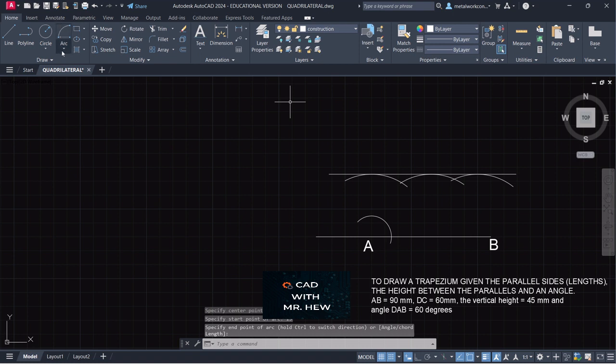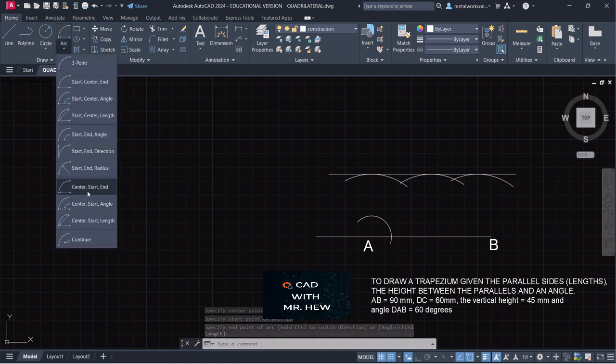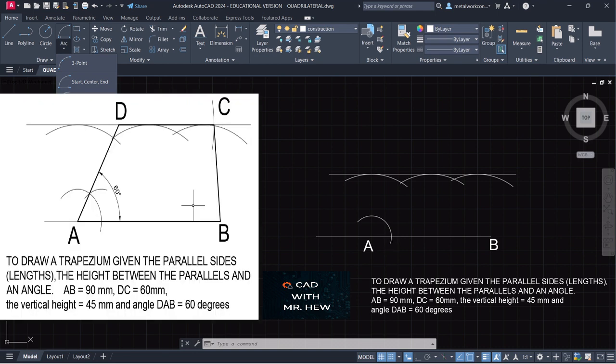What we're gonna do, we're gonna draw another arc with the radius equal to 15 from the intersection where the arc intersects the line AB. We're gonna mark another arc. So the center would be at the intersection. We need to turn on our snap. This radius would be 15. So we'll come here and mark that. All right. The line drawn from A going through the intersection here, that is 60 degrees. All right. So the line from here to there, that's 60, enter.